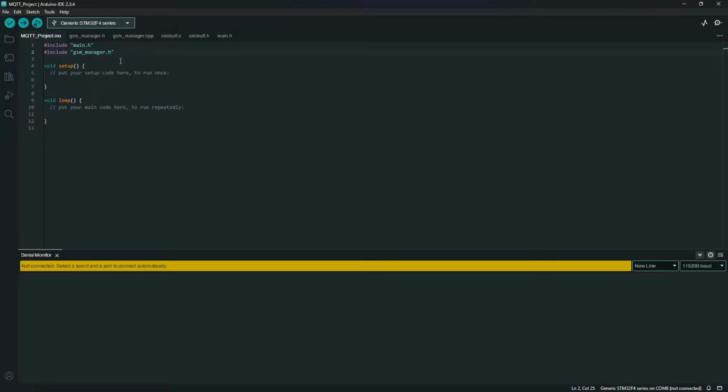After that, we're going to set up one or two other things required for our MQTT project. One of the first things that we're going to set up with that is going to be our MQTT session variable. So with that, that is going to be called GSM MQTT client simcom underscore connect session. So this is the variable type that is used to define everything that is part of the MQTT session. So I'll go into a bit more detail once I've finished writing this line of code.